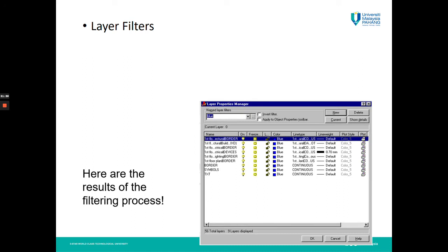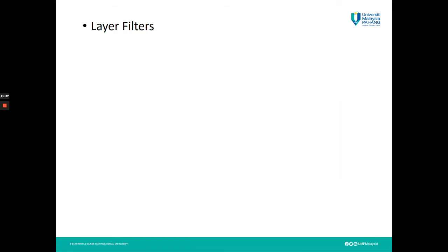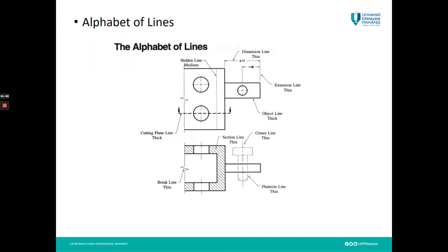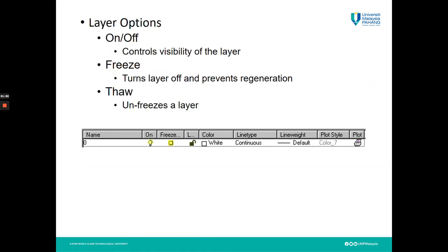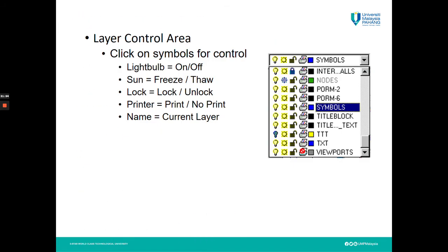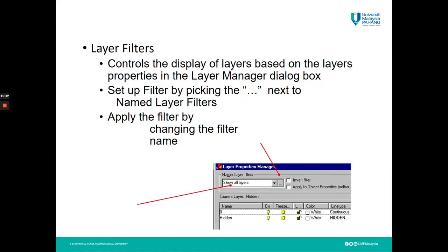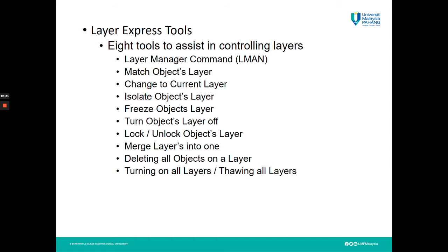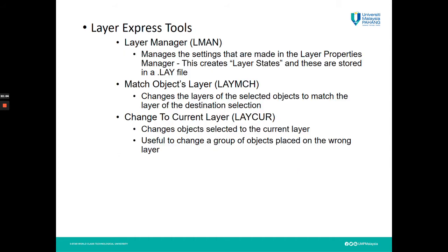Okay, I will give you an exercise. Do the layers one by one until 8. No, not this exercise, the line exercise. Do all the line exercises like this one, all these 10 lines, and make layers for all of them. Name them one by one, and then color each one differently. Now that is one way to do layers in AutoCAD.